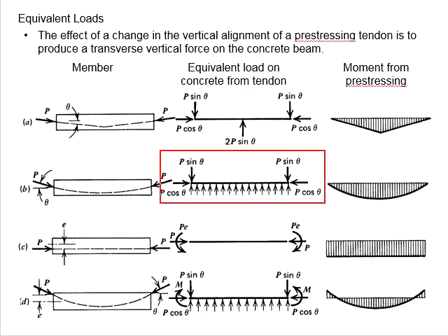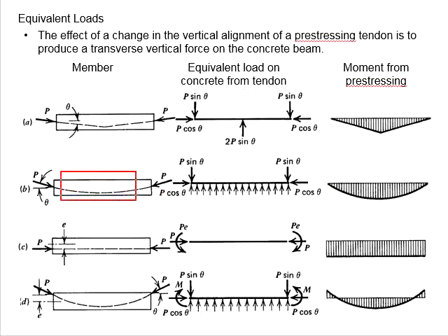A similar concept is applicable for the other tendon profile. For the curved tendon profile, the gradient angle of the tendon changes gradually until there is no gradient at the midspan. Such a process of changing of the gradient will result in a UDL equivalent load acting on the member. A similar concept applies here. In this case, the eccentricity is put above the neutral axis.